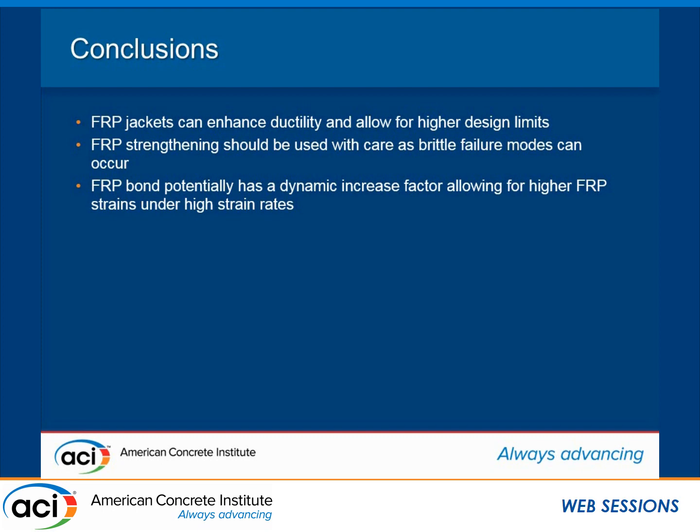Very nice. A suggestion. In terms of the connectivity of the CFRP, you're using some sort of epoxy or adhesive. What about mechanical connections on top of that? Sure. That is absolutely something that you should be concerned with. In fact, back to the Canadian thing in CSA S8 06, which is the design for FRP, it says you can design up to this limit for flexure unless you provide some sort of anchorage, and then you're on your own for that part. This didn't include the anchorage, but anchorage is the obvious next step past studying the nature of the bond. I think with the mechanical connection, you probably get much better results. I agree.